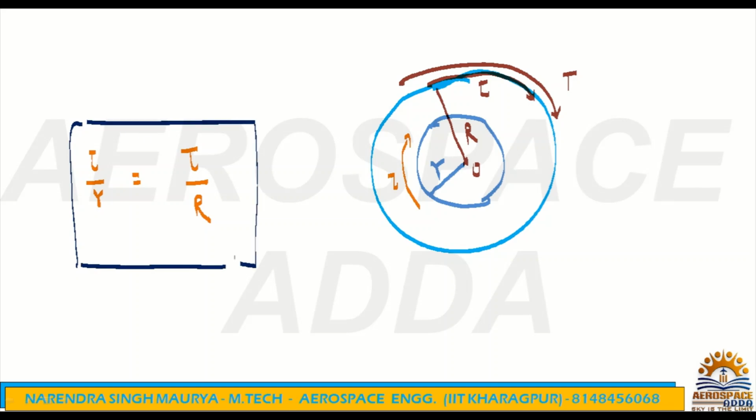Capital R is nothing but the surface of the shaft. Capital R is the radius, but small r is any radial distance. Nothing to worry. I can say this is tau at small r, and this is tau at capital R. So this tau is the shear stress for small r radial distance, and this tau is the shear stress for capital R radial distance. Capital R means you are on the surface of the shaft, and small r means somewhere inside the shaft, any radial distance you are taking there. That should be very clear. There should not be any doubt now.